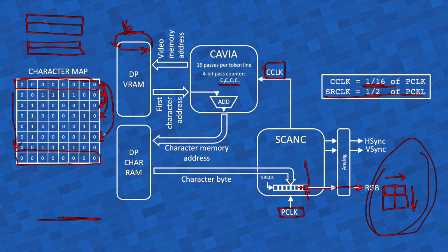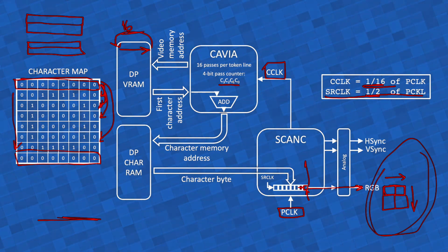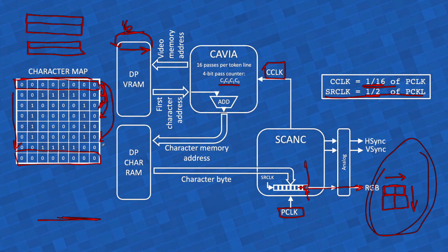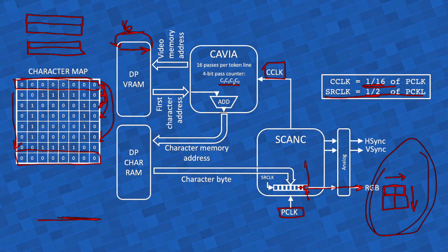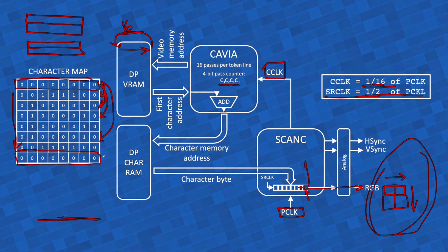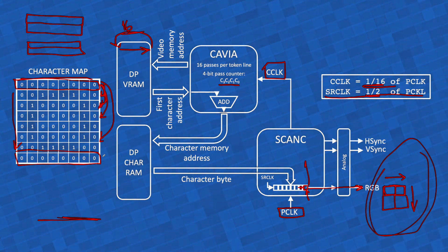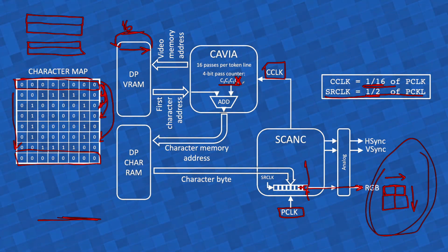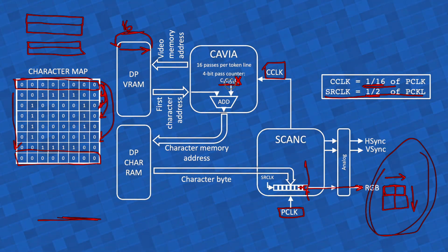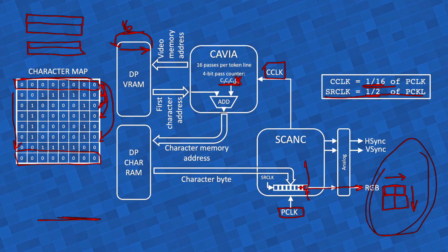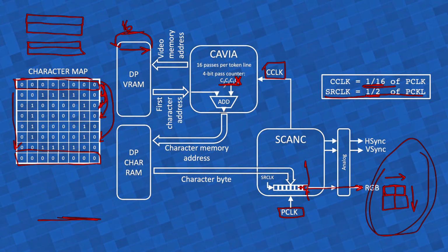But what should we add? Should we add all the 4 bits? Of course not, otherwise we would end up adding 15 and we have to add at most 7. The whole thing starts from 0. There is a simple way to solve this. We just ignore the least significant bit when we do this addition, and we just take the other 3. 3 bits will count from 0 to 111, and 111 is 7. And that will have the exact effect we're looking for.